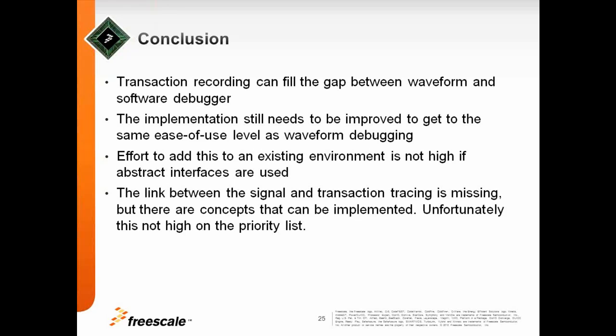The other thing we have seen, since we do not use UVM, and the question is whether the things you really want to do are designed really ground level things or easily handleable in UVM as well, is that it's possible to add this into an existing environment to enhance the debugging performance. But, and that's the other thing, and also one of the requests I made to Synopsys already, there is this link missing between this waveform debugging and the transaction debugging. So I want to click on a signal, and I want to get through the transactions up to the line that basically issued the whole thing without 25 clicks in the middle.